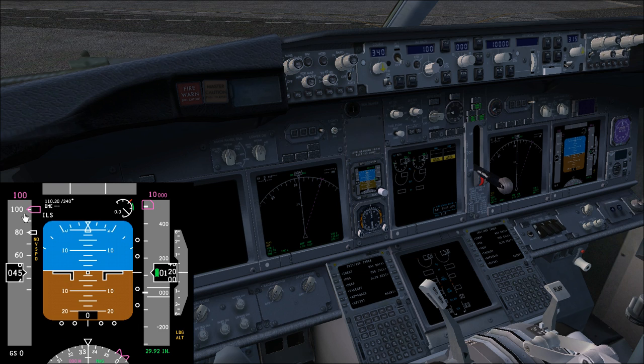Then we have a tape. The tape is provided with 10 knots increments, and as you can see now we have this white indicator that is actually set on 80 knots. That is the takeoff roll check for speed at 80 knots. You can set it also on 100 knots. The same type of indicator is also set for V2 plus 50 knots or 10 knots based on the options of the aircraft, and actually will be seen while on climb out after the takeoff.